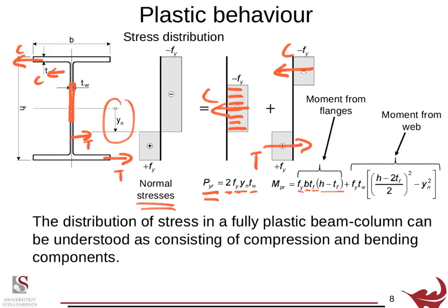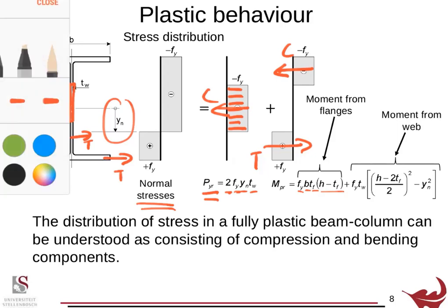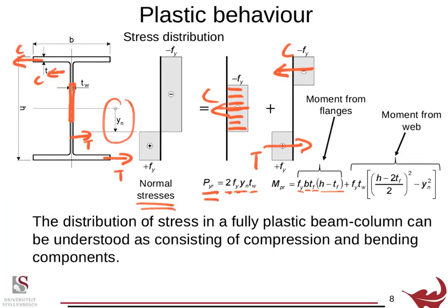And it'll be the same even if you have an asymmetric section. For instance, if this is not symmetrical, what you would have to find is a similar scenario, similar behavior, where you're going to have some area carrying the moment, and area carrying the compression. And then the area carrying the moment has got to be the same. So area carrying moment in compression equals the area carrying moment in tension. So we have equilibrium, and then also the area in compression you would find based upon how much moment is being carried.